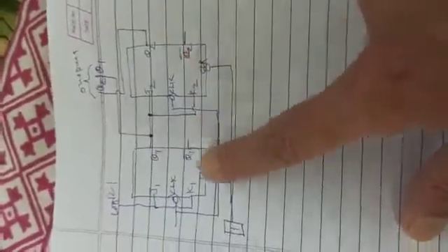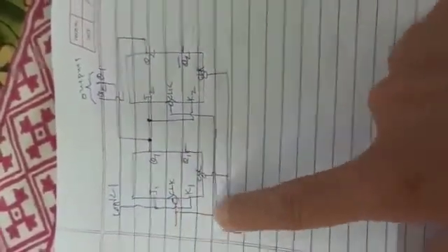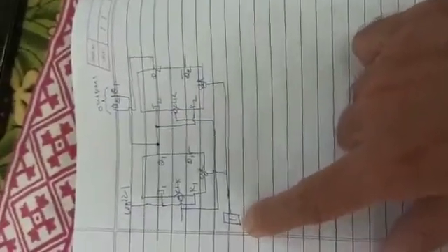And then we can have a logic diagram. So here two flip-flops are required, so we are using two JK flip-flops. Being synchronous, the clock is given simultaneously to both the flip-flops. Okay, so the clock is given here. For J1 K1 we got the expression logic 1, so that's why logic 1 is given, and for J2 K2 we got the expression Q1, so here Q1 is given to J2 and K2. The output is taken from Q1 Q2, so here you will get the count. The clear input is shorted and connected to logic 1 while it is counting. If it is connected to 0 or if a 0 pulse is given, it gets cleared. Okay, but here we don't use reset logic. So this is a mod 4 synchronous counter.